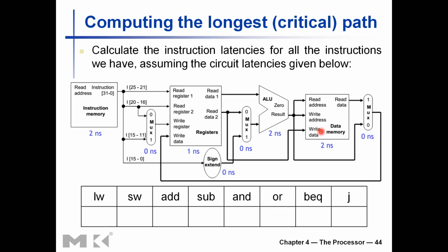So the time consumed for the writing happens in the next clock cycle, which doesn't really matter if the time taken for the next instruction to be read and the values along these address lines to be updated is larger than the writing time.